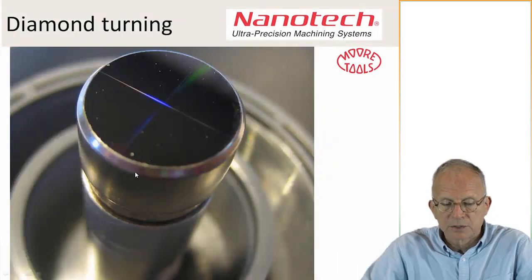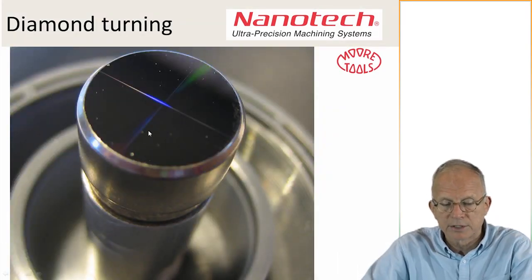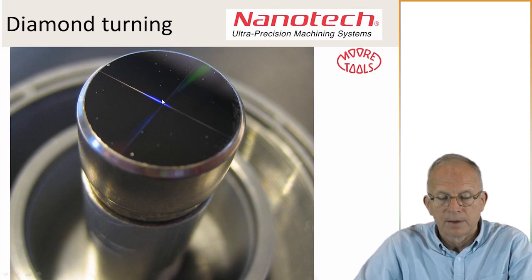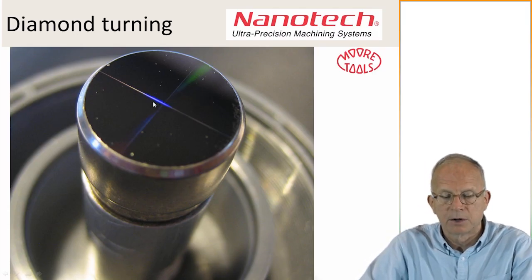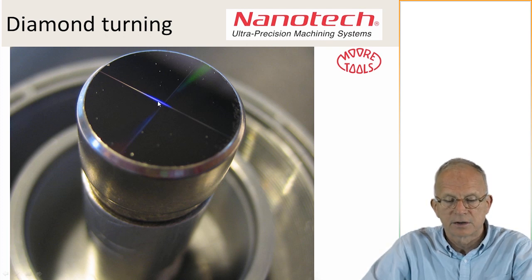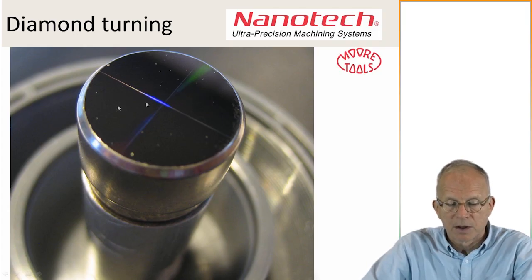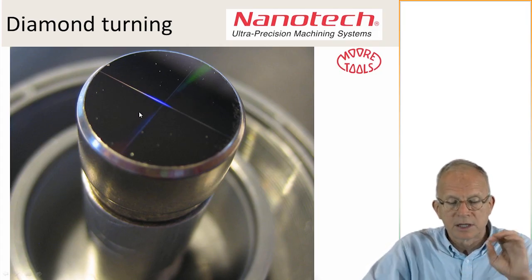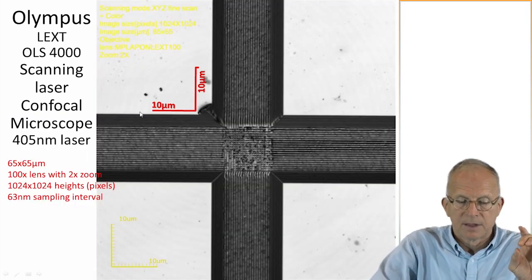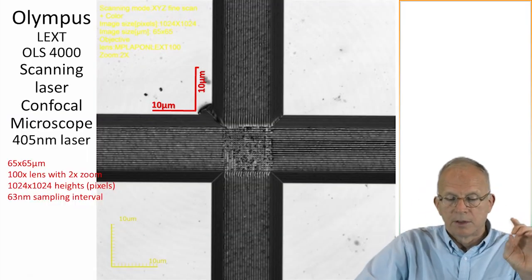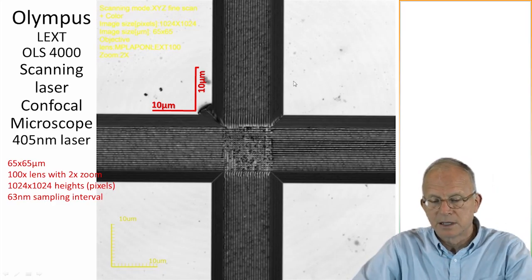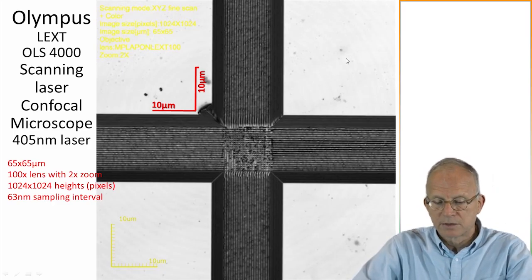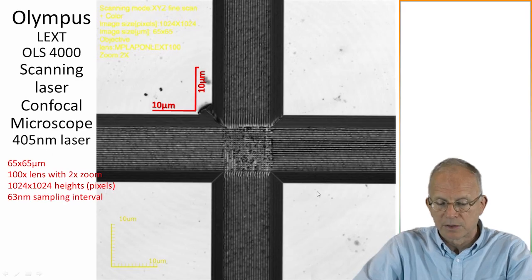Now, if we take a closer look at this, we can see there seems to be a cross on here, which is blue. And that's because we're looking at 500 nanometer grooves on here, and that's reflecting as blue. This has been faced with the machining operation. So first they went round and round to face this so that it's smooth. Now the material here is electroless nickel, which doesn't have any grains and is single phase. So it can come out as being quite smooth. Now perhaps on your monitor you can't see this, but we can see the rings from the facing operation, just barely out in these quadrants here.